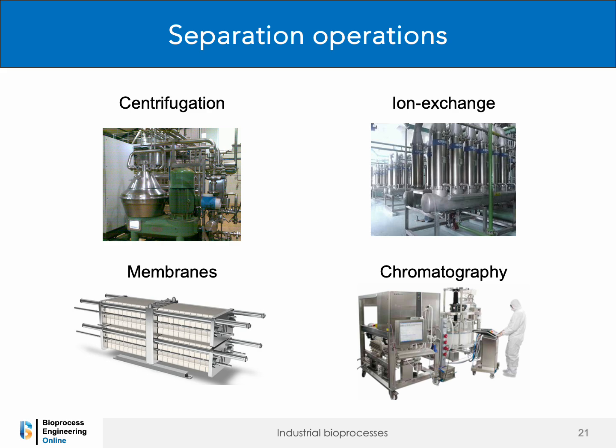Furthermore, bioprocess separation operations incorporate more biospecific methods, such as membrane-based purification, which includes microfiltration, ultrafiltration, nanofiltration, reverse osmosis, dialysis, and electrodialysis. Additionally, chromatographic purification techniques play a vital role to reach high purities, encompassing ion exchange, hydrophobic, size exclusion, and affinity chromatography.